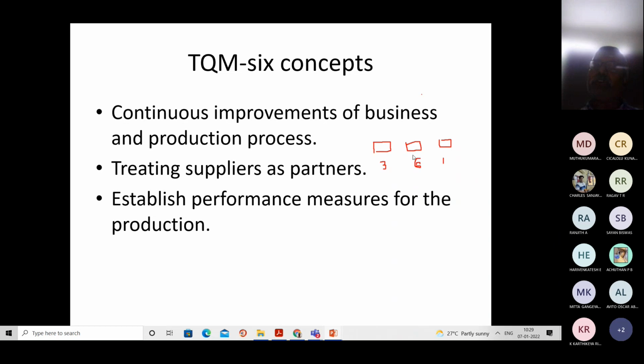So one product will go to the oven. After the first one, every 6 minutes two breads will be ready, two sandwiches in the unbaked condition. So here the semi-finished product will wait, and here this person will wait. All these things we can improve. There is a lot of scope for this. This is called balancing of line.